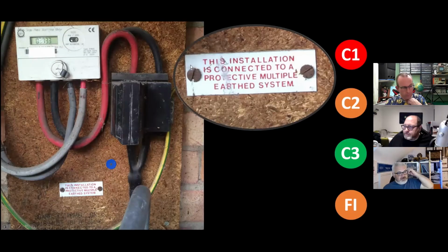Interestingly though, these cutouts were available for a number of years, where you would have plastic around the side and then the exposed earth connection on. You don't see many of them anymore, because they don't comply with current standards. But I just thought it was really interesting. The cable comes through 2 layers of heat shrink on the cores there. Most of the time that would be behind mechanical protection again. But a lot of them are just these single floating cutouts with an exposed earth. So what would you code it as?